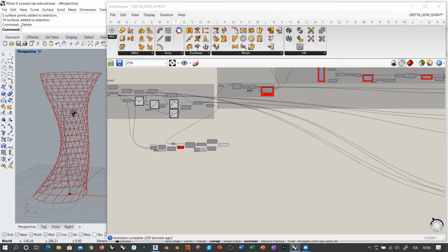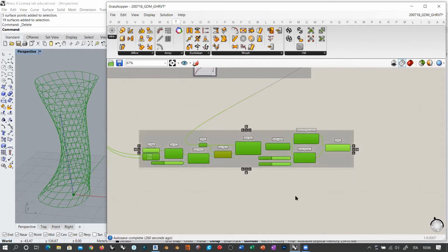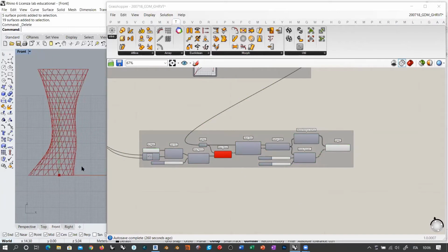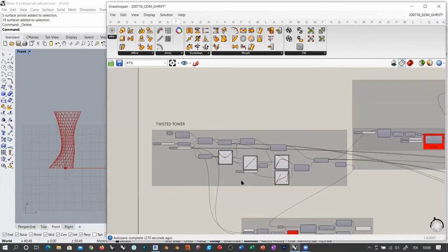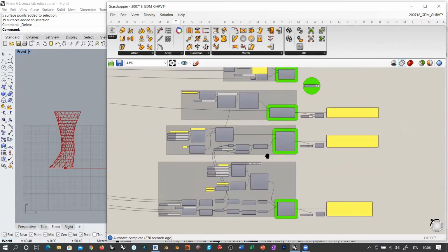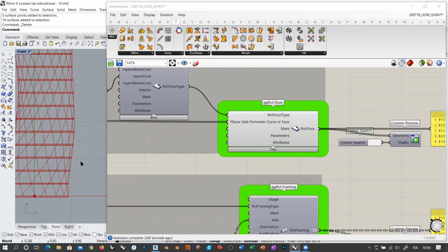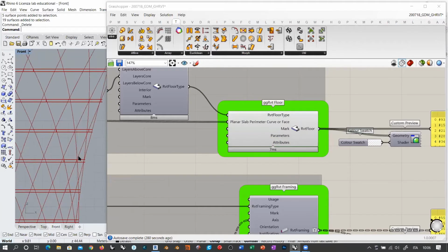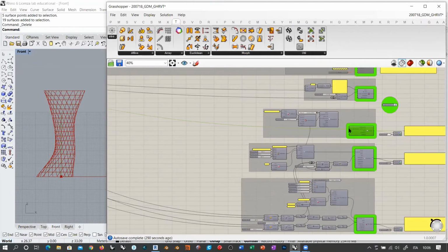So this could be another approach to paneling. In order to get a simple geometry, and also try to solve some practical problems, like having this division here correspond with the level height. So you see that it is 3.5 meters. This is going to correspond with Revit levels, where we already have the floors. So you can already see that the panels correspond exactly to the presence of one floor. Everything is working perfectly with this paneling.